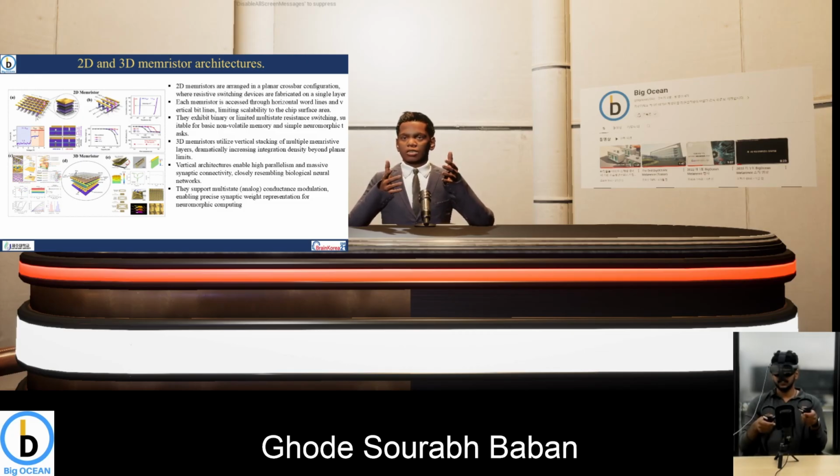In 2D memory, each cell is accessed through horizontal word lines and vertical bit lines, limiting the scalability to the chip surface area. Also, they exhibit binary or limited multi-state resistance switching and are suitable for basic non-volatile memory and simple neuromorphic applications.